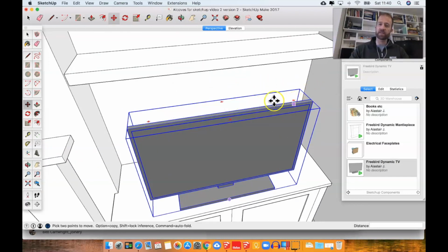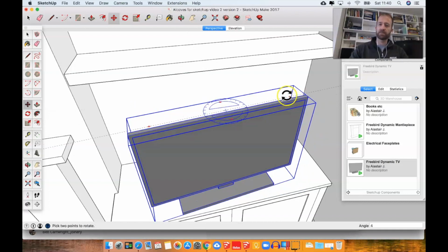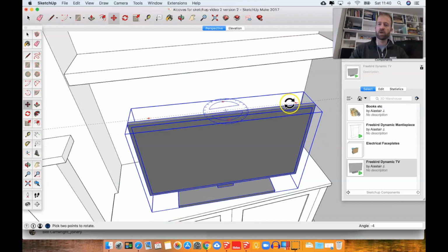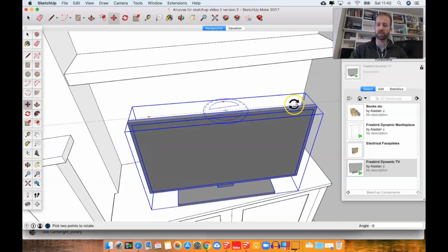Now this is a perhaps lesser known function of the move tool, that when you're on a group and you just hover over, you come up with these grab points that are a quick way to rotate, either freely or, once that's active with one click, you can just type in an angle, say -5.